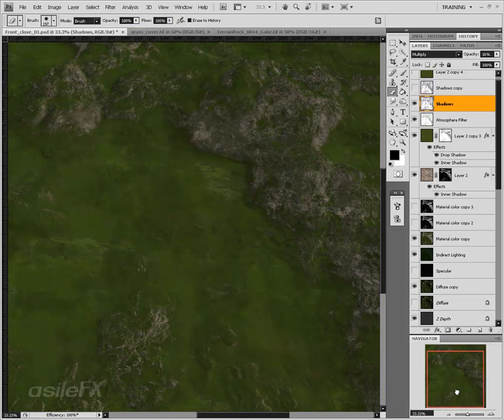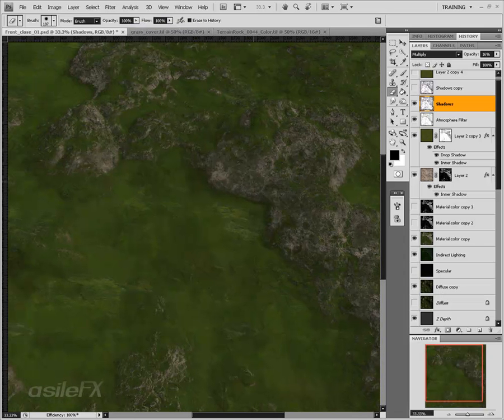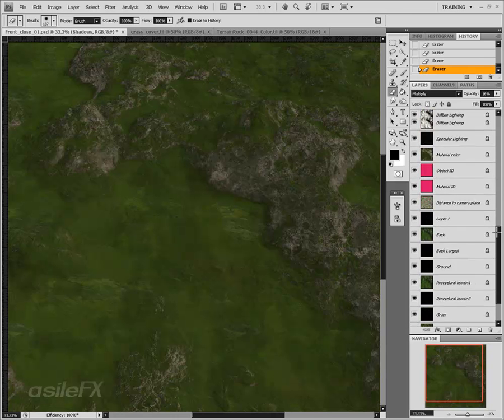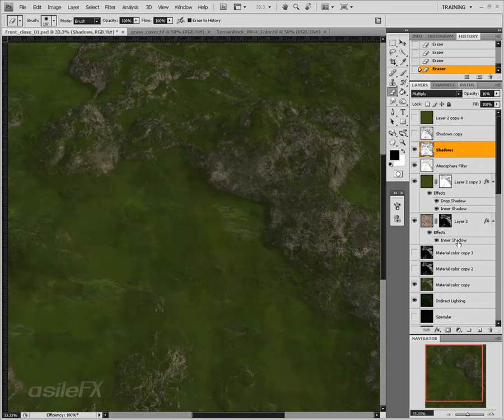When you're working with a large amount of these images, sometimes you just want to save specific layers out. So what I could do is create a duplicate. If we go over to the history, create document from current state, which is available in the history in this bottom button here on the left, and then delete every single layer we don't need, so all these other ones, and save it as a different file. That way our texture maps and all that are saved, but we don't have these huge files, because this file itself right now is a little over a gig.